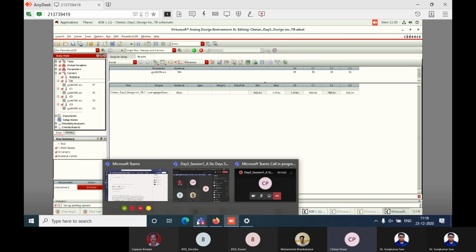Good. Now one net should be what? The output net is selected there. Now you need to select the input net, right? So you can copy paste the signal one. No, no, that equation. From here also you can copy, no issue. Overall, you need to select it. Yes, Control C. Paste it in signal 2. And what is your signal 2 net name? Instead of B, give that net name.